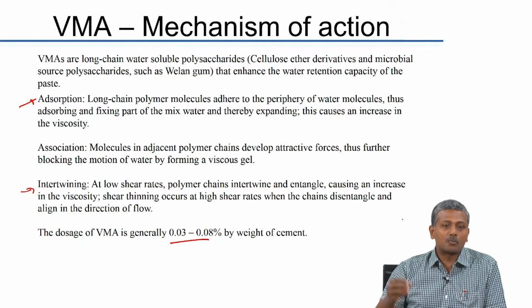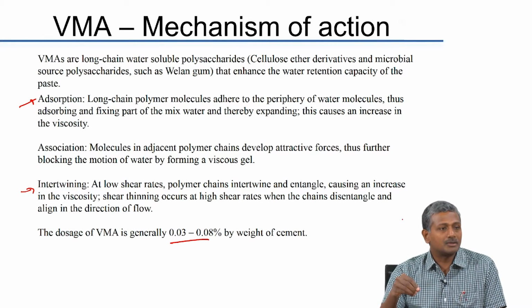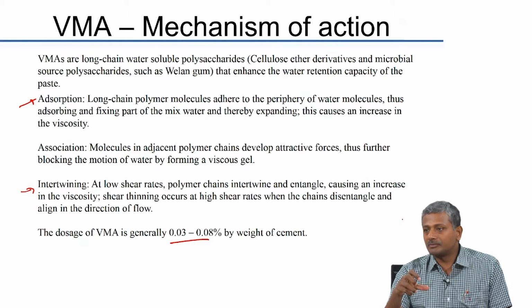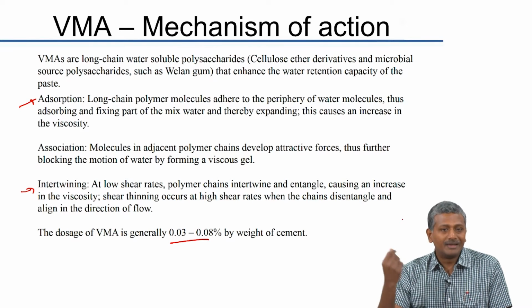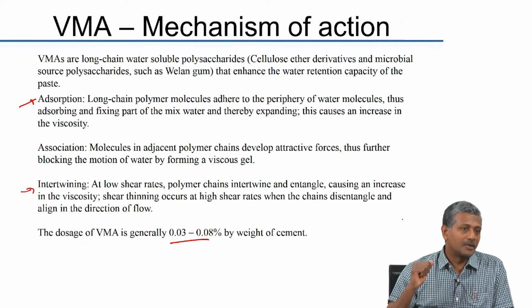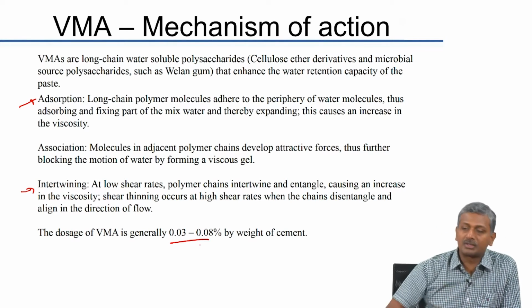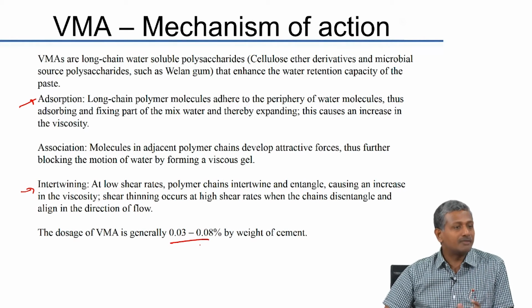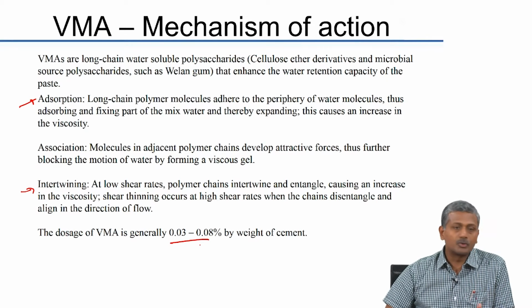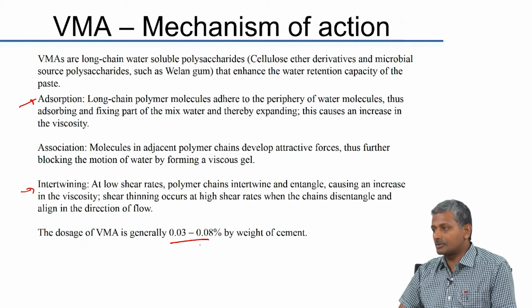If you have to disperse a small amount of powder inside your concrete, it is going to be quite difficult. But if you have to disperse a liquid, all you have to do is mix it with the mixing water and it can get dispersed quite easily. So, VMAs also, although here I am talking about the dosage in terms of the solid, are available as liquid solutions from most of the construction chemical manufacturers.